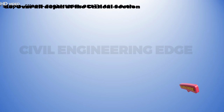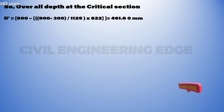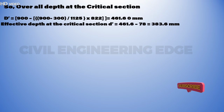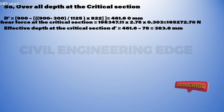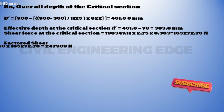Shear force at the critical section = 198,347.11 × 2.75 × 0.303 = 165,272.70 Newton. Factored shear, Vu = 1.50 × 165,272.70 = 247,909 Newton.